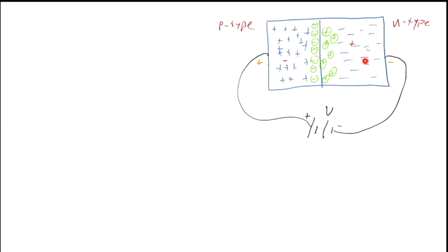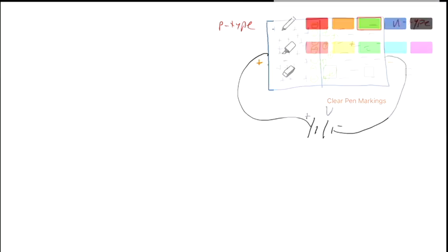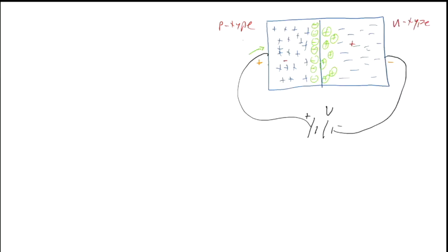If that seems confusing, if we've got a negative charge here, that repels electrons. So these free electrons are pushed away from this negative charge. And over here, these positive holes are pushed away from that positive charge, right? They're not attracted, they're pushed away. So we're going to have holes going in, and we're going to have electrons going in because we've attached this battery with this polarity like this, right?